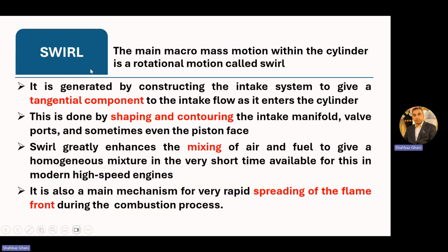Now, swirl. The first and most common motion happening inside the cylinder is the swirl. The main macro mass motion within the cylinder is a rotational motion called swirl. It is generated by the construction of the intake system to give a tangential component to the intake flow as it enters the cylinder.